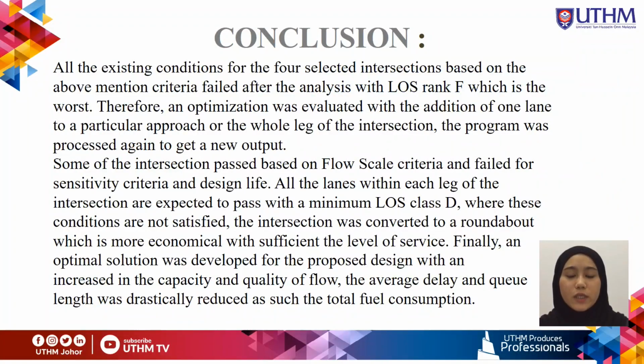In conclusion, all the existing conditions for the 4 selected intersections based on the above mentioned criteria fail after the analysis, with level of service rank F, which is the worst. Therefore, an optimization was evaluated with the addition of one lane to a particular approach or the whole leg of the intersection. The program was processed again to get a new output.